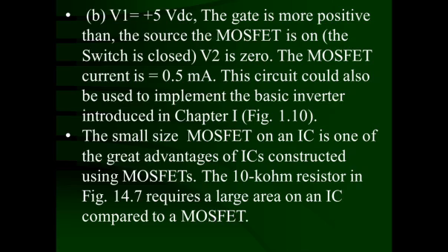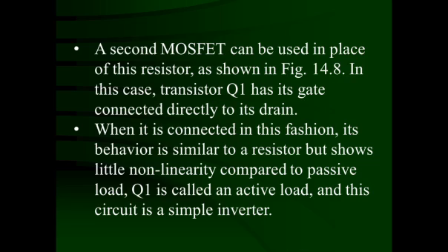That's why in LSI, large scale integration circuits, VLSI and super LSI, that means very large scale integration circuits, more than 1000 gates for the chip, more than 10,000 gates for the chip, or microprocessor chips, where the number of gates required is very large, then it is better to utilize CMOS technology rather than TTL technology, because they require less room, so more gates can be packed on the same amount of chip.